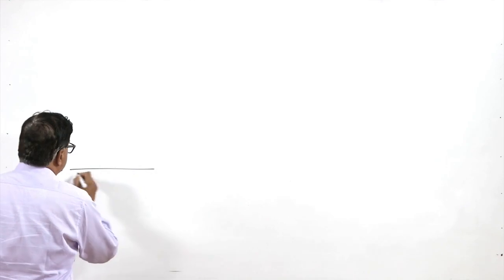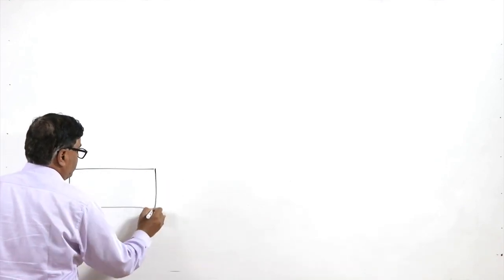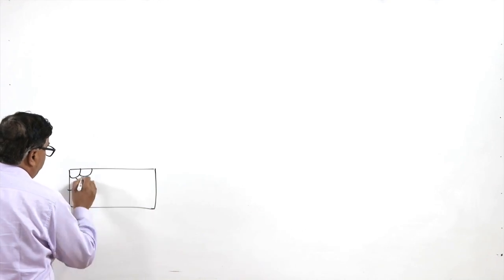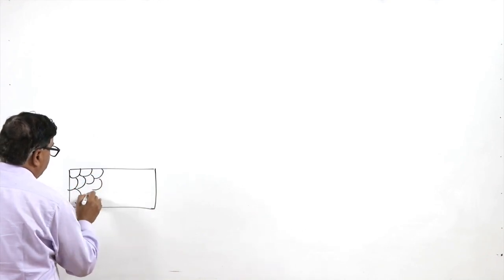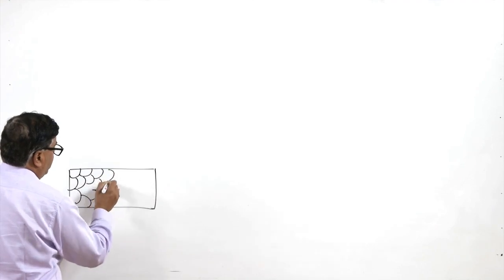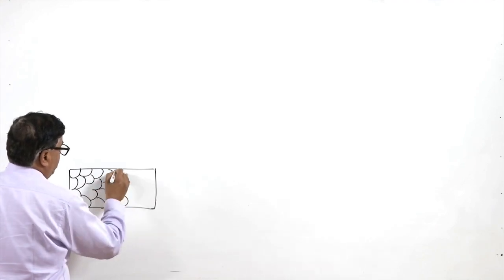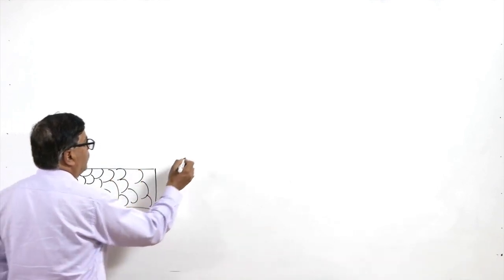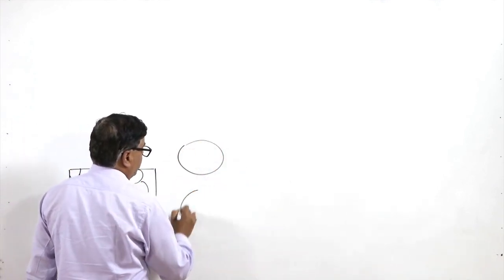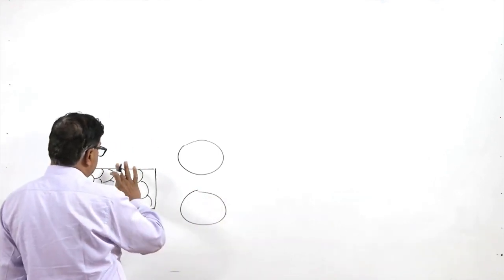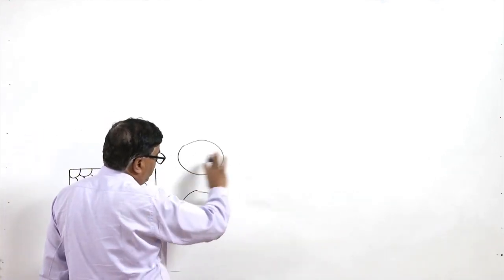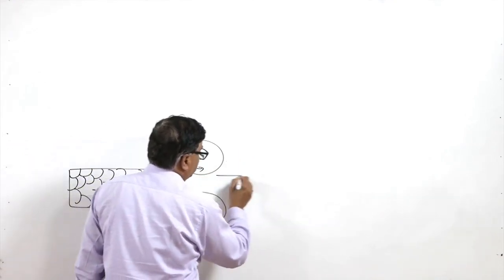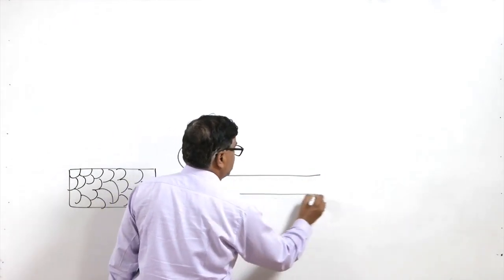Say in a simple ingot made by casting, the structure will primarily be equiaxed, but when it is subjected to plastic deformation, say it is rolled down to a smaller thickness by passing through two rollers, thickness is reduced and length is increased.